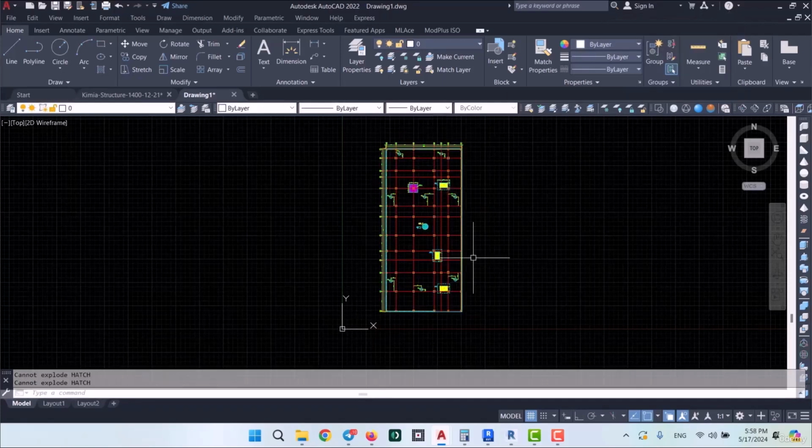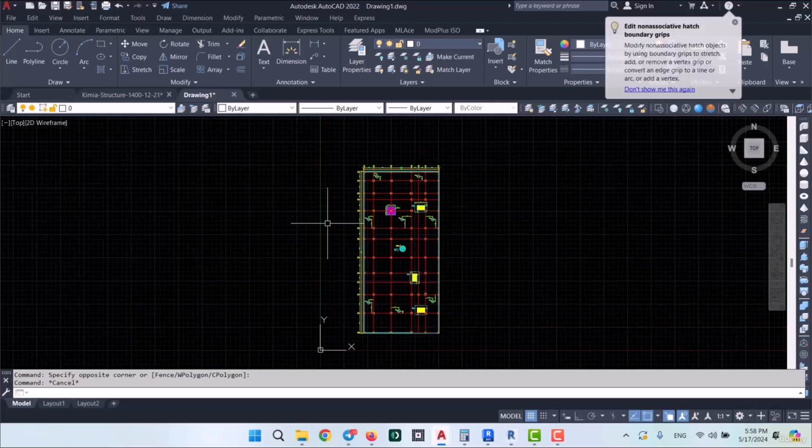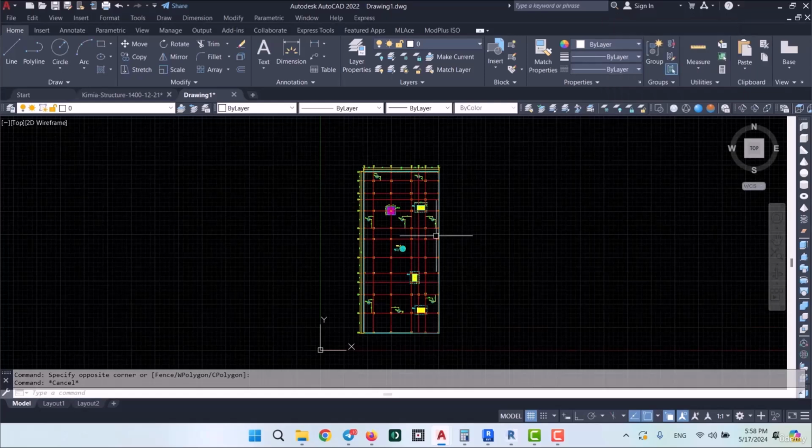So that's enough, and now for the next step, we're going to have to specify the 0 point. You see, when you try to import your CAD plans into Revit, it's important that your plans have the same 0 points so that all the plans will be aligned together in different levels. Now that we know how important that is, I'm going to specify the 0 point. Now usually we decide for the crossing points of the horizontal and the vertical axis of the plans as the 0 points, unless you're already obligated to choose a certain point for that.